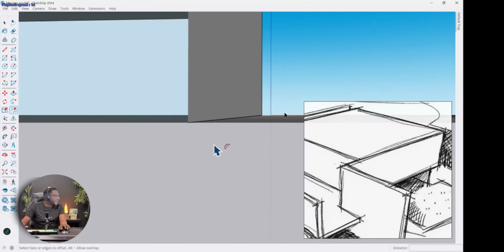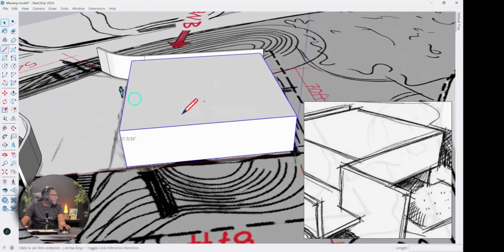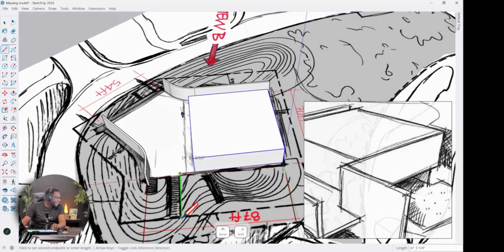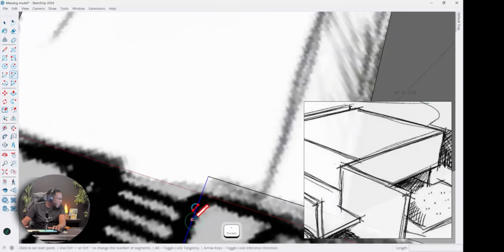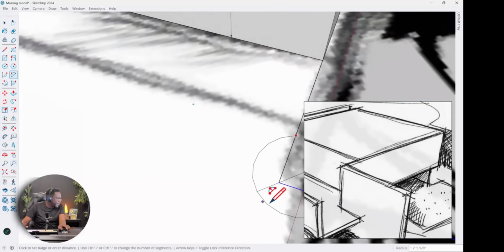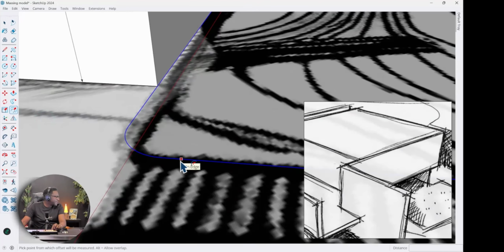And if I zoom in here, let's draw this line again, because that's why we're getting that error. So I'm going to draw that like that and like that. There you go. And let's put that curve in. Oh wait, it's right. It has to be perfect. This can be tricky. You have to make sure that it's flat. I think that maybe could have been the issue. All right, offset. There we go. Works fine. And we'll make that 1 foot.